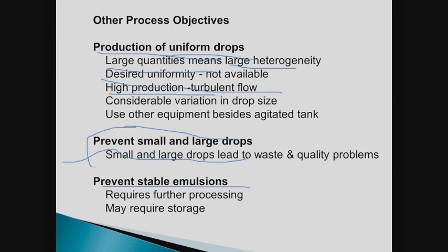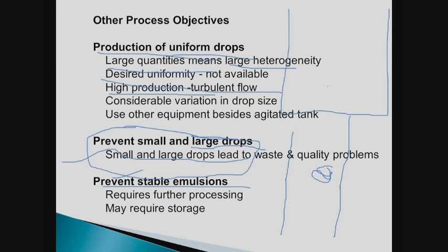One thing here for the static mixers. If I take a look at a static mixer, I can't have a big drop in the static mixer. The static mixer won't permit me to have a big drop. It will break it up. So one of the advantages of a static mixer is you don't have the large drops. You may have the small drops, but you won't have the large drops. The agitated tank, remember our glob of material sticking to the wall? Now that glob of material will be there. It may still be there as we speak, 20, 30 years later. So there's a problem there.